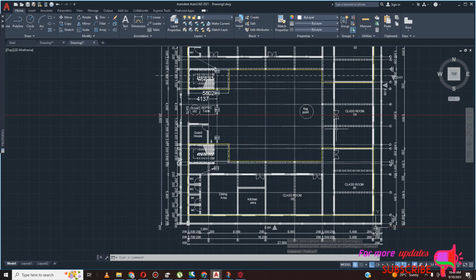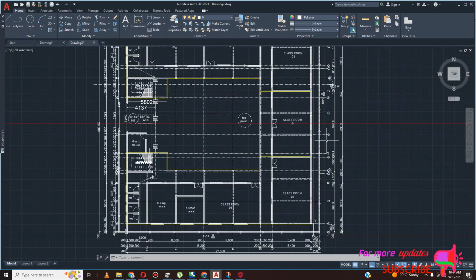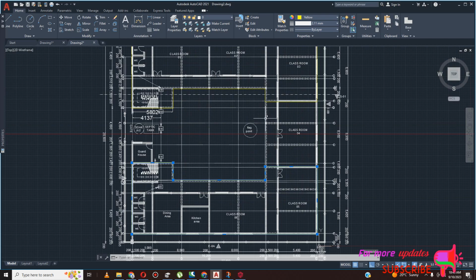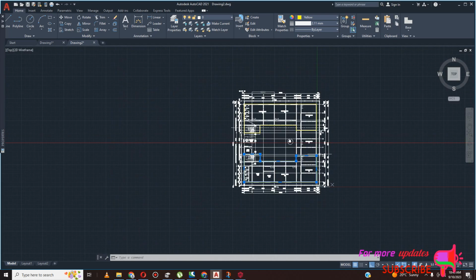So what we need to do, we don't need to model the entire structure. We can model it halfway, right? Because they are symmetrical in the structure. But the only trick here is that you need to model two structures, and the other one which is symmetrical to the other, you will just use the same design. So you need to model this, and now this here, because there is no other symmetrical object with it.